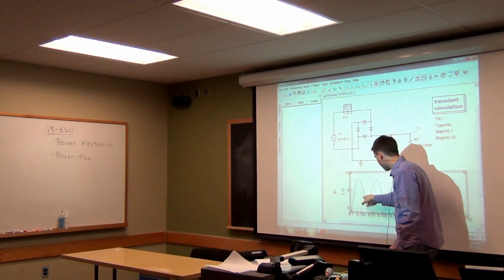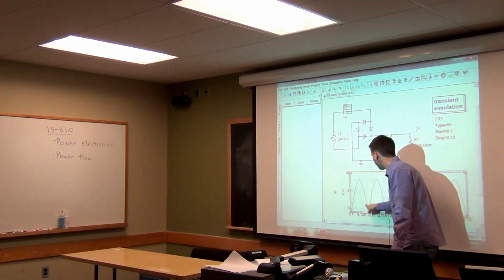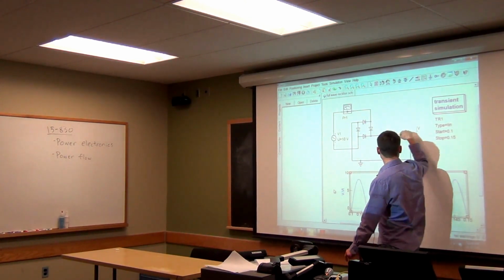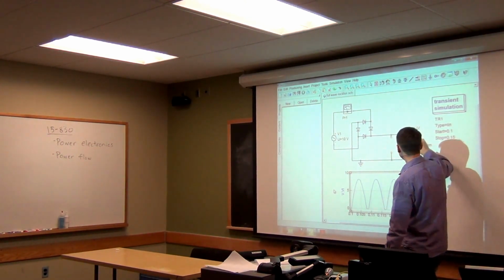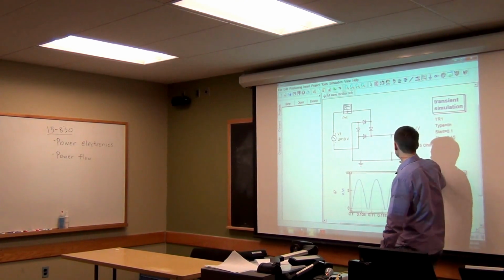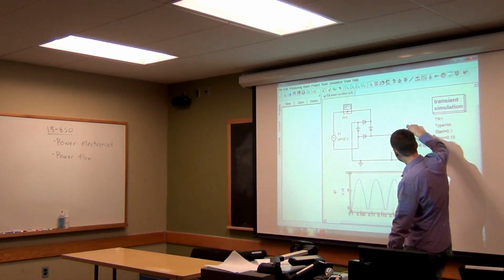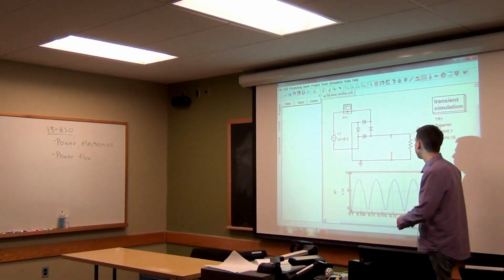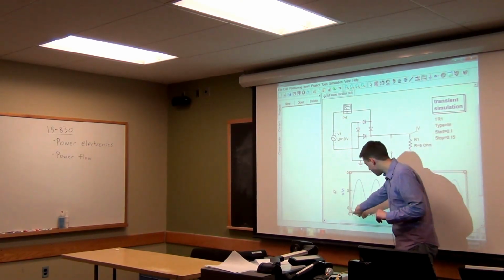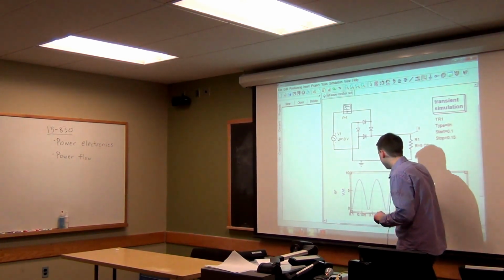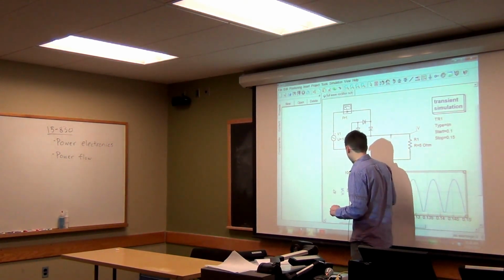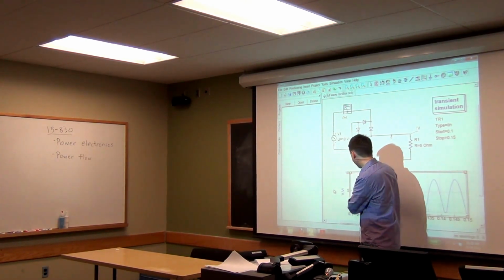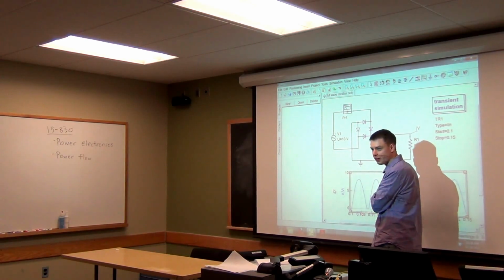We see this voltage here that is always positive. So that means we're putting a reference ground there. So it's always going to be higher here than it is down here. This side is referenced to 0. But for every phase, what's really happening is the voltage source is going up and down here. When the voltage is positive here and negative here, we get this half of the wave here, and similarly the other half.